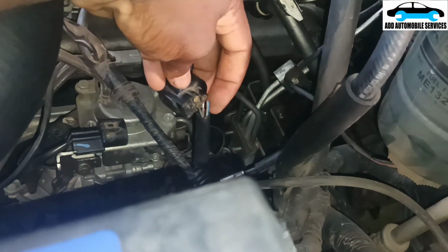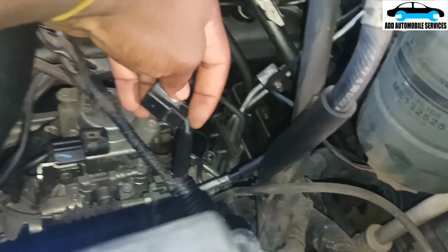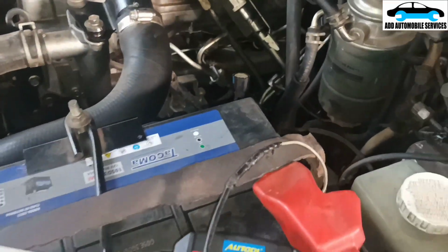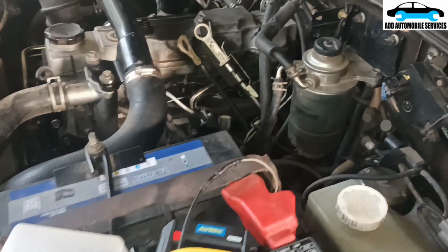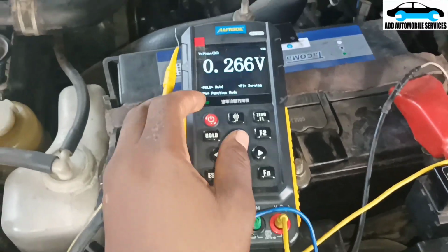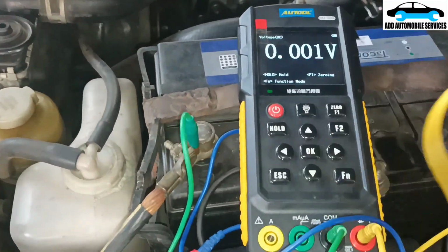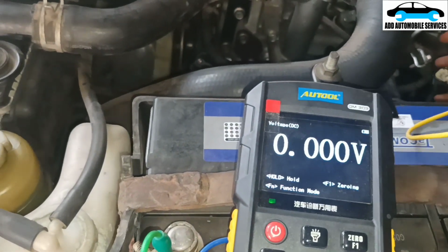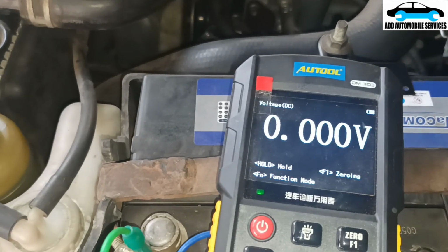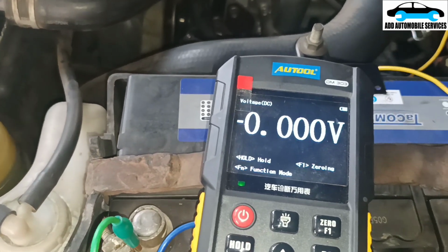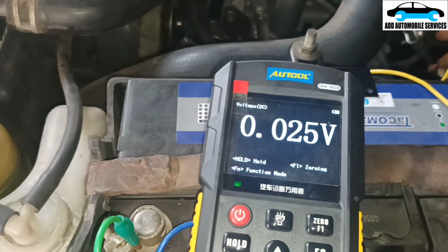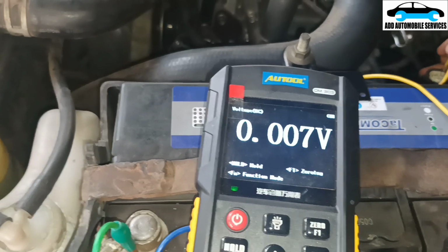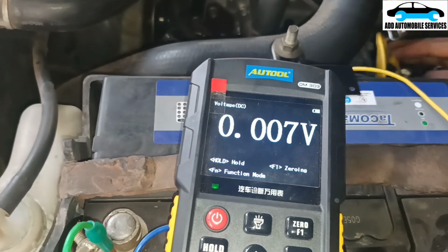Wow, okay, it looks like one wire is broken here, and what I'll do is test the other voltages also. Let me bring the scan tool. Let me test it first. So I set my voltmeter, then I'll start measuring the voltages. One side is on ground, so let me measure the first pin, and that's the broken wire. I'm having 0, and this also, I'm having 0.1. So this could be ground, and I'm having this also. One could be ground and one could be signal.